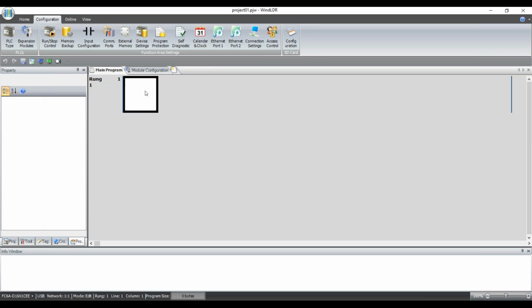The first thing I'll do is a convert data type instruction to convert the temperature data that's coming in from an integer to a float. Then I'll also do a division instruction to convert that into the real temperature. Remember, we need to divide it by 10 to get the real temperature. So let's do that. Maybe I want to do this once a second, for example, and you can decide how often you do it in your program. I'm just doing this as an example, so I'll grab the temperature once a second. For a real application, maybe you want to do it every 5 seconds, 10 seconds, 30 seconds, a minute. It just depends on the application.